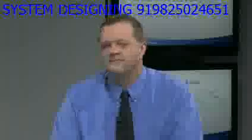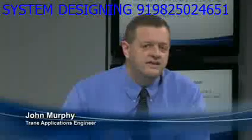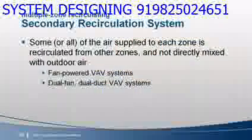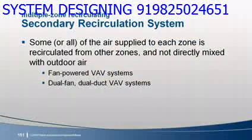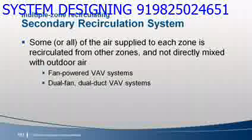John? To review what Dennis shared during the main program, in a system with a secondary recirculation air path, some of the air supplied to each zone is recirculated from other zones without directly mixing with outdoor air at the intake. The most common examples are VAV systems that use fan-powered VAV terminals, which draw recirculating air from the ceiling plenum. Two-fan dual-duct VAV systems are another example.